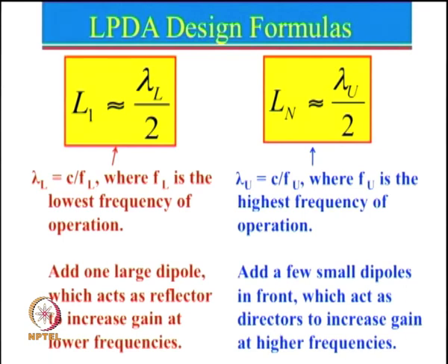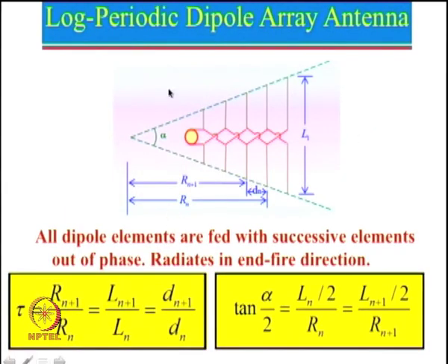Again, let us just look at the figure back here. So what we are recommending is that after this dipole antenna, put some more elements. The reason for that is, think about this: if we just choose this as the highest frequency dipole antenna, then there is no director in front. Now apply the logic of the Yagi-Uda.